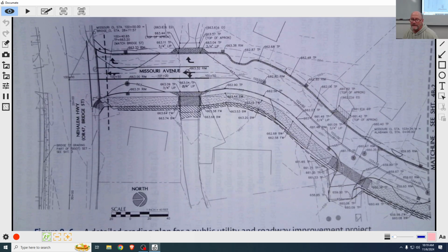Okay, well, here's a plan view, right? So plan is just top view. Like mechanical terms, that's top, front, side. In architectural and civil terms, you're looking at plan, section, and profile views. So section view would be like the right side view, or just a side view, if you will. And then a profile would be a front type of view where you see elevation change.